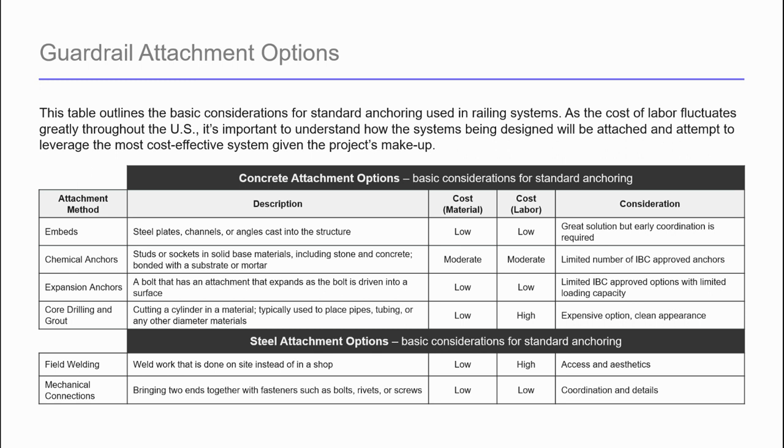Again, on an exterior application, very high wind loads, for example, you have a windscreen, it might be 6 feet tall rather than the traditional 3.5 feet tall for a guardrail. You get very, very large loads there. And again, it's suggested that you contact a competent professional early. You want to avoid potential problems later in the life cycle of a project. For example, changing a concrete slab or having to go through a concrete slab to steel below. Very difficult and expensive to coordinate.